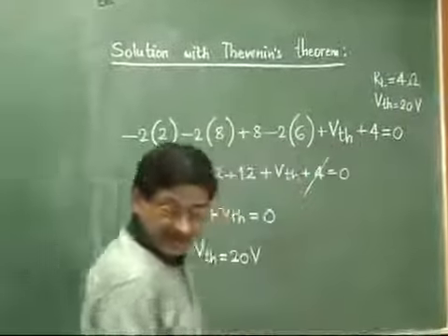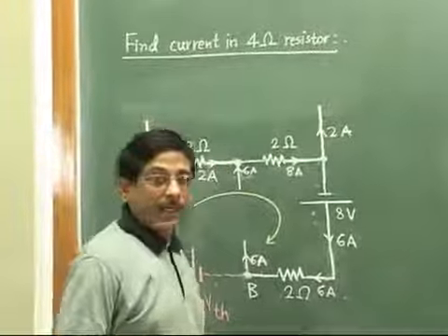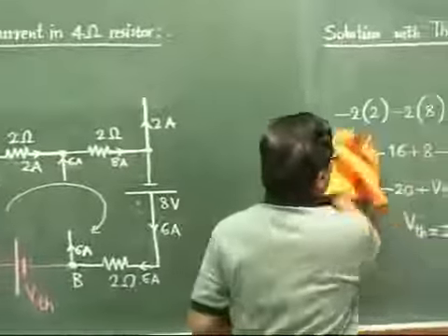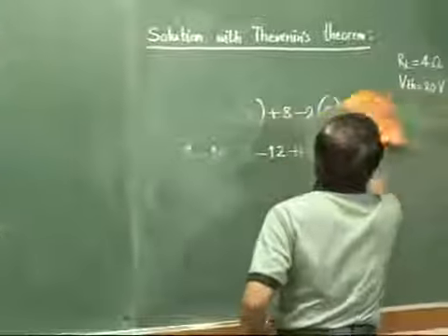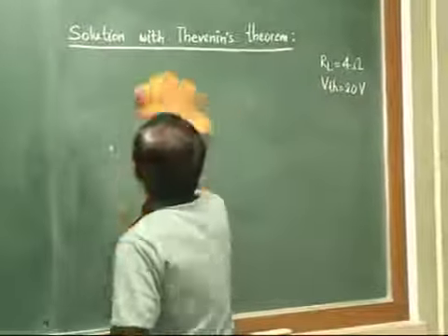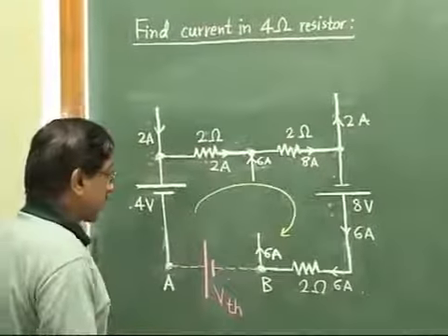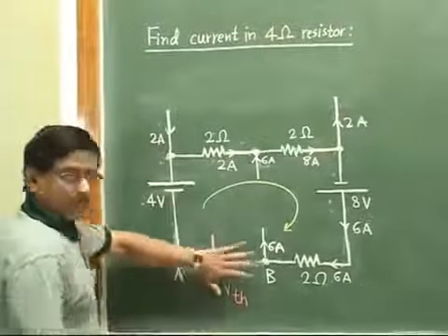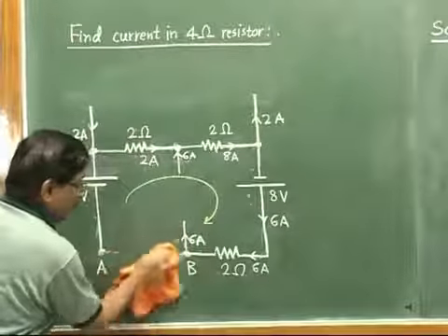And now the next step in Thevenin's solution is to find the net equivalent resistance of the entire circuit across those two open points A and B. And we have to take only passive circuit for that. Okay. So what we have to do? Only take the passive circuit. So this VTH, we don't want all this now. We want just a passive circuit. So we just remove it.